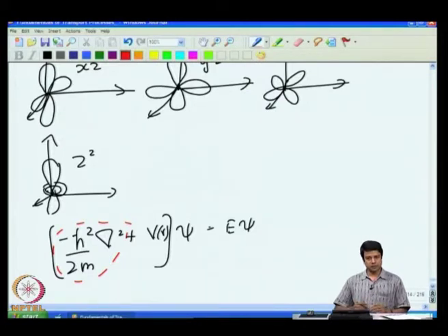If we were solving a problem within an object of finite size, then the solution would only contain the increasing harmonics, because the decreasing harmonics actually go to infinity at the origin. So, if the temperature is finite throughout the domain, we can have only the increasing harmonic solution. On the other hand, if we are solving a problem outside an object such as a spherical particle, we can have only decreasing harmonic solutions, because the increasing harmonics will go to infinity as r goes to infinity.